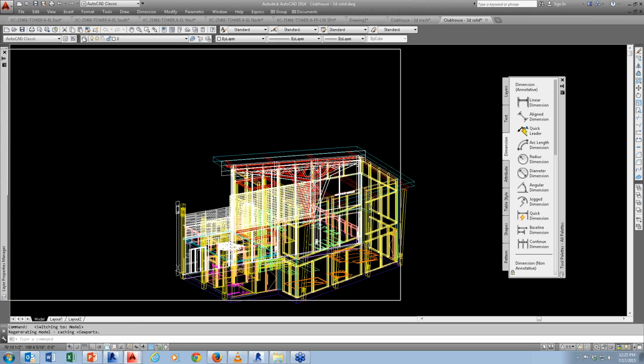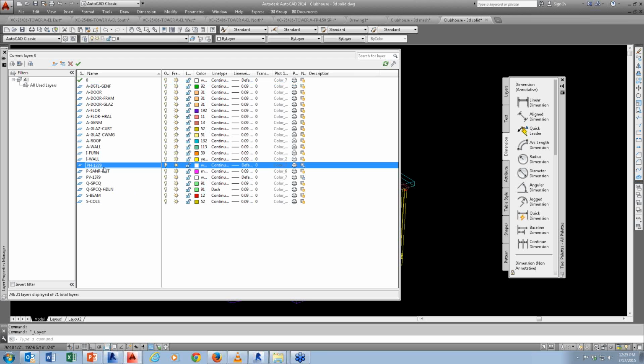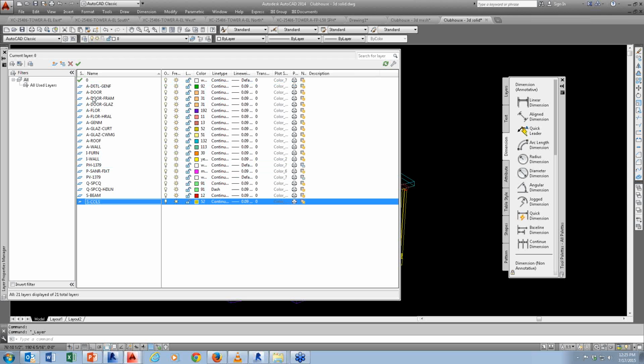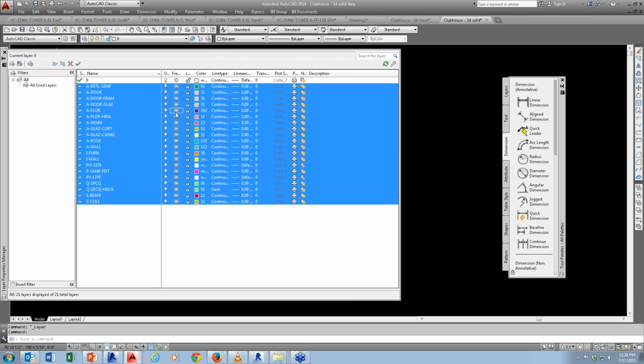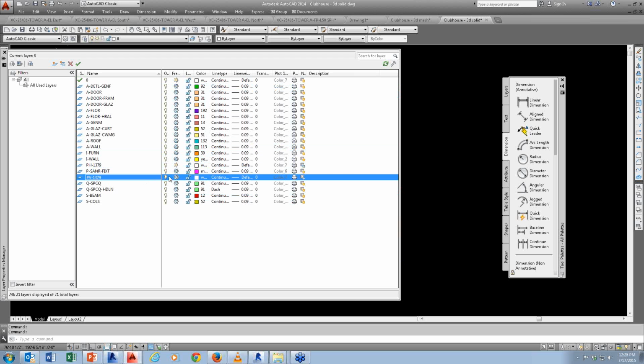You can see, I'm going to turn off the layer. It's going to create one called, where's the 2D layer? This is the one, PH, that's the hidden, and then the PV. I'm just going to turn this off, and then just turn on the PH, and then the PV.